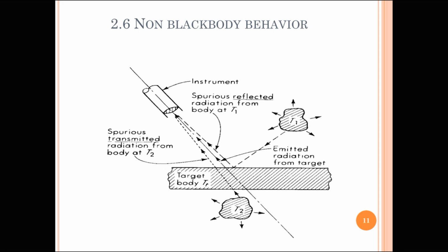Since in this method we are using the instrument itself to determine the emittance, there is no question that we are using the correct type of emittance. The radiometer emittance dial is adjusted until the temperature indicated by the two instruments agree. If there are no changes in conditions, this emittance setting can be used for any future radiation temperature measurement without requiring the presence of the thermocouple. Since emittance can vary with the temperature, such an emittance calibration may be necessary over the desired temperature range.